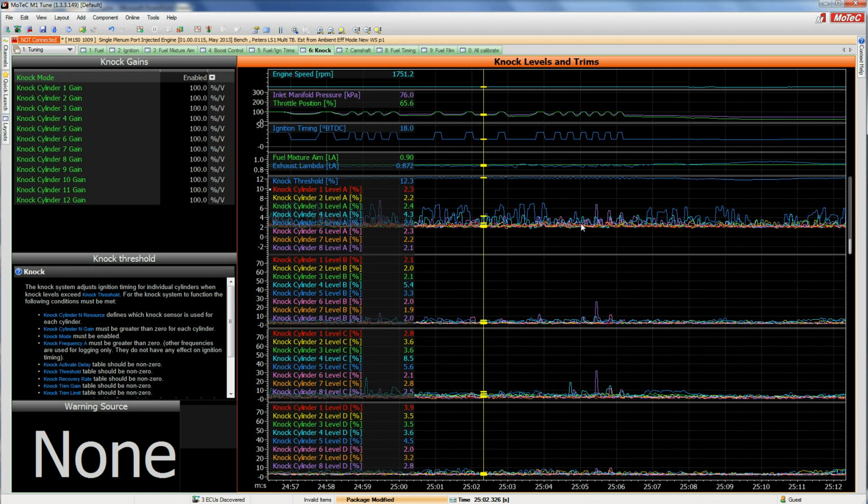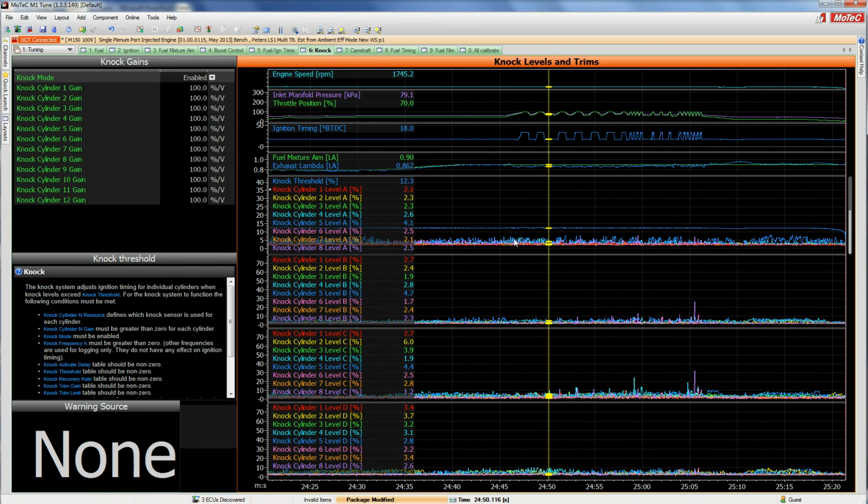Now, because on this particular engine the location and quality of the knock sensor mean they're all pretty close, certainly for this test, we didn't need to do that. To calibrate the system properly, you would go through a full ramp and look at those individual gains and balance them as well as you can. Alright, just unzoom that back again. You can see eventually, if we were to do a full ramp run and the background noise with no detonation was similar to this, you want to change your threshold level to be just above that, say 5 to 10% above, and you definitely want to make sure that the threshold would be crossed by any knock event that happened. So the threshold in this particular case, you would want around that kind of level where I've got the mouse.